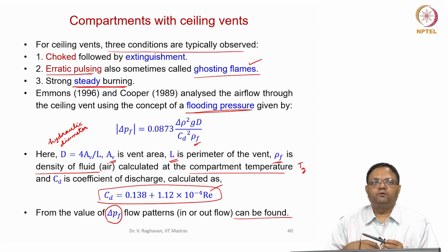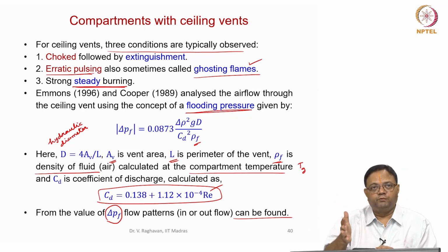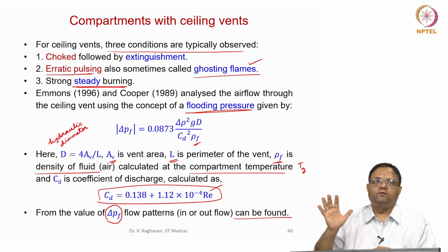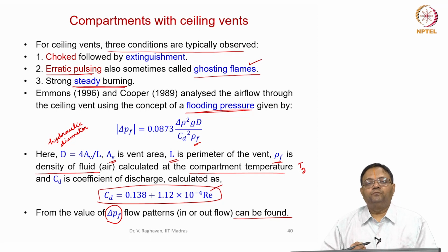So in compartment fires, due to the enclosure effects, several types of behaviors are observed. This behavior differs when there is a growing fire and before the flashover occurrence, and after flashover it goes to a fully developed fire. There the situation is different, and all this depends upon the venting conditions.